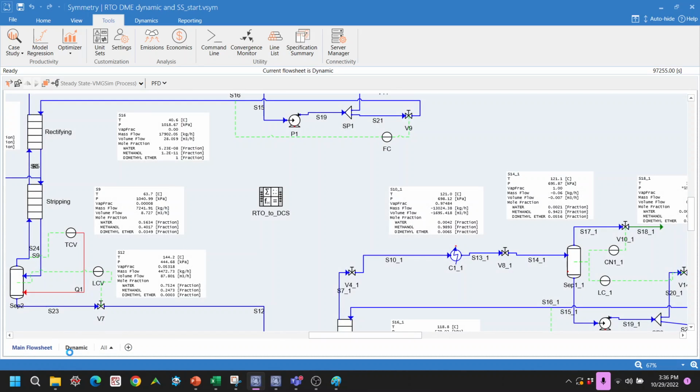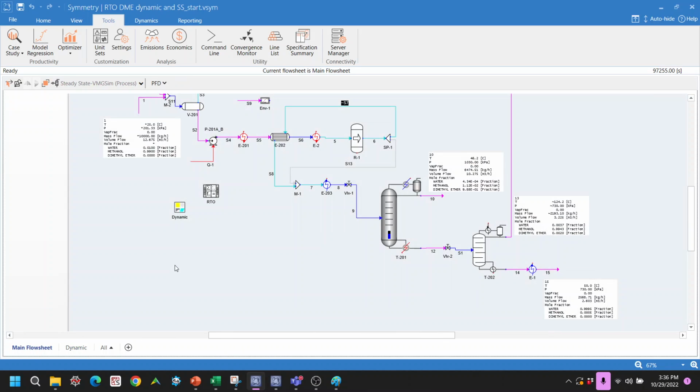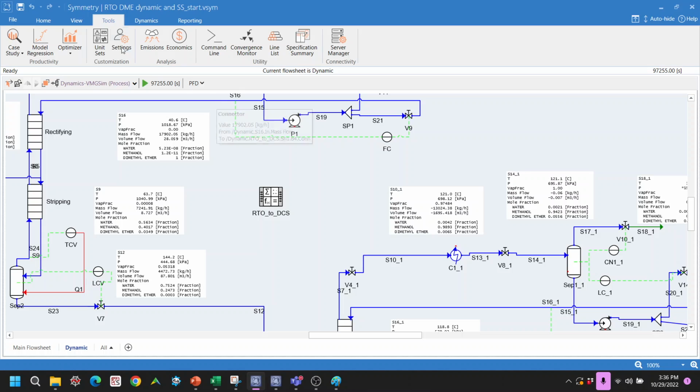Now I can go to the real plant. Why can I go to the real plant? Because from a chemical engineering point of view, we know the purity is strongly related to the reboiler duty, and reducing the reflux ratio will also reduce the purity. It will reduce the reboiler duty, and it will save us some money. So the result of this optimization is consistent with our knowledge of chemical engineering. Hence, it is accepted as a solution. So now we get the solution, we go to the plant. This is the plant, so let's run this plant.